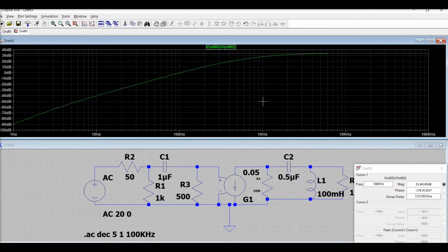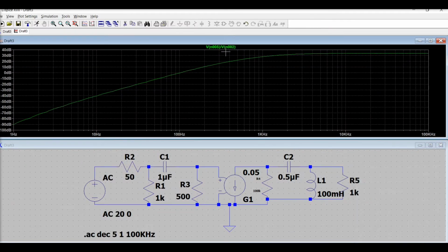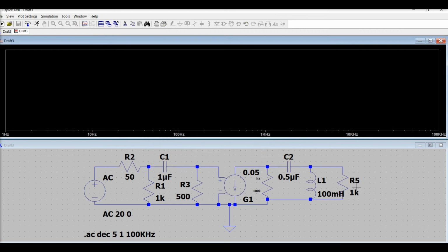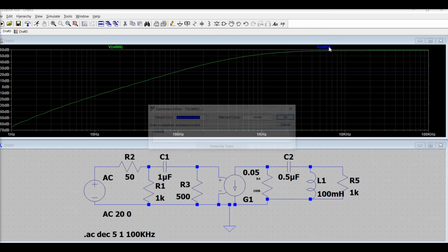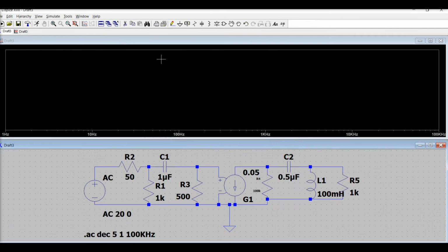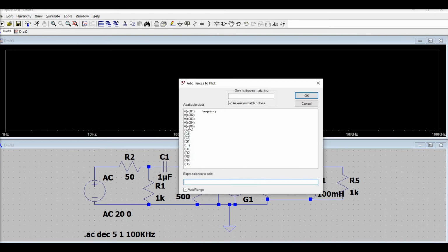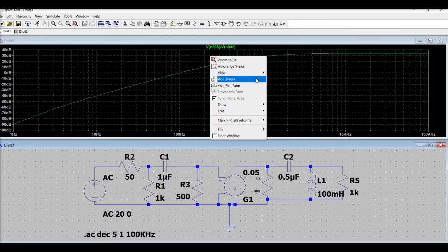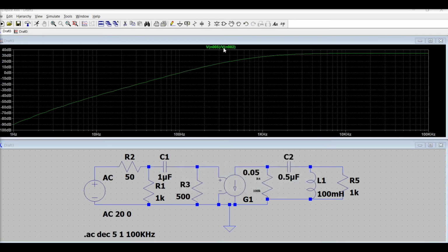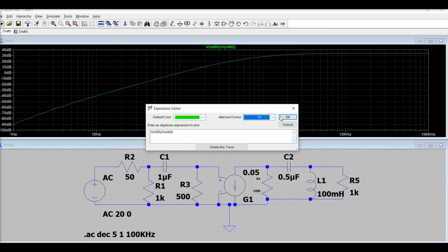So I'm going to switch over to LTSpice. Over here I just did nothing. If I show it to you again, what's happening is I first want to know what this node is. When I clicked it, it's 005. When I click this one, this is 002. So I have to find the ratio of these, right? Right click, delete, and then right click, add traces, V(N005) divided by V(N002). The trace comes up, and then what you have to do is right click again, then add trace, not add traces, sorry. So add a cursor, let's say.